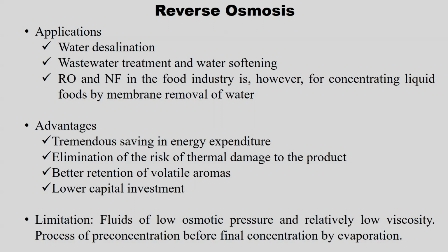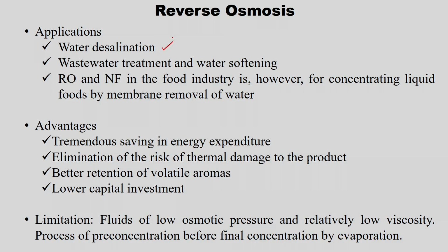Today we mostly concentrate on reverse osmosis and nanofiltration. Both techniques have much overlap, and I will explain the exact difference in a couple of slides. For reverse osmosis, the major application is water desalination, which we all know. The moment we say reverse osmosis, the first thing that comes to mind is water desalination, and also wastewater treatment and water softening. Water softening is the removal of unwanted ions from the water.